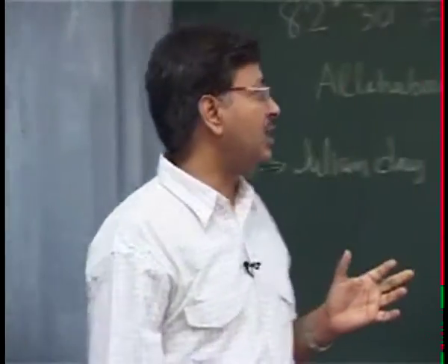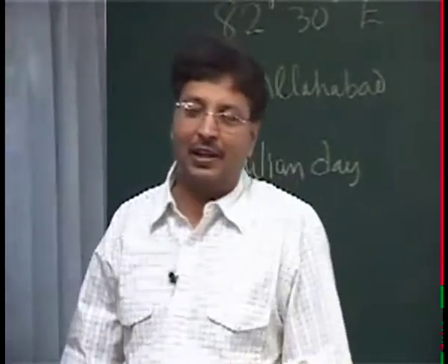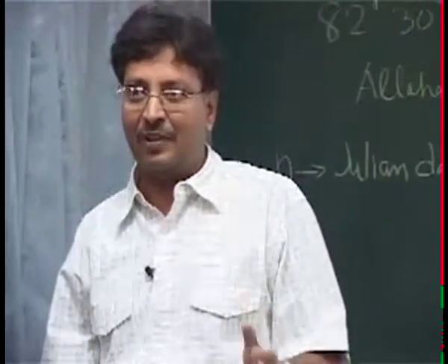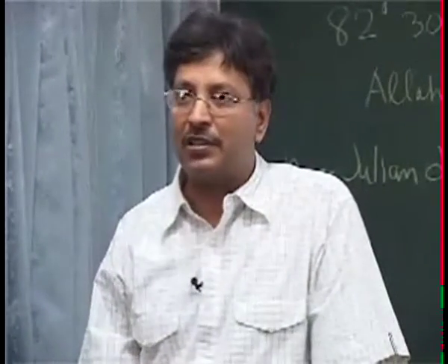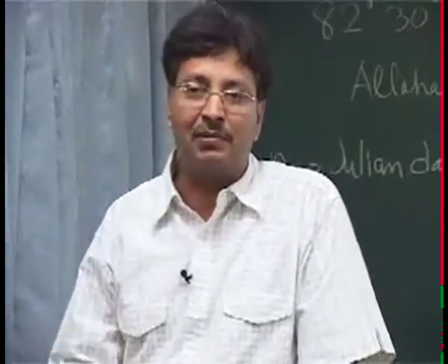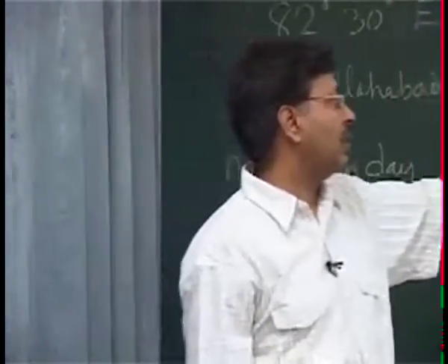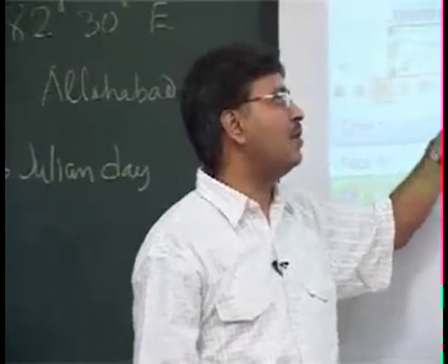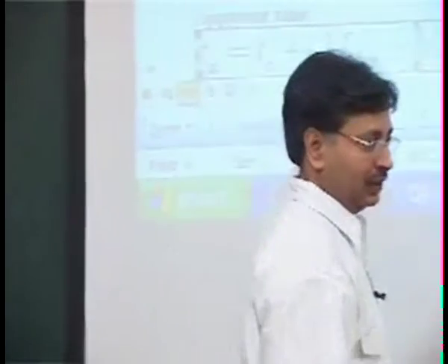So that is how you find your apparent time, or your real time. Of course, for convenience, we have the standard or reference time, but we are trying to estimate something else for which I need apparent time. So this is your standard time, correction for meridian, correction for the sun's position. Is that clear? Let's go further.